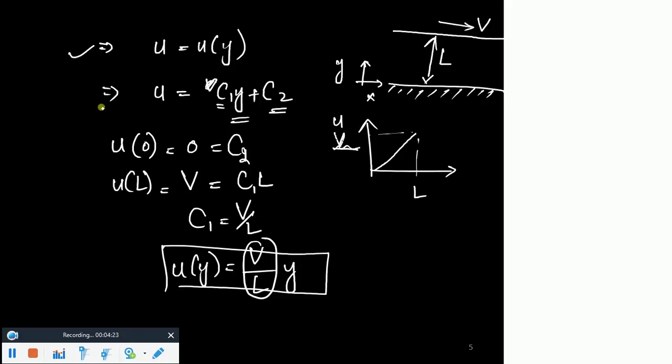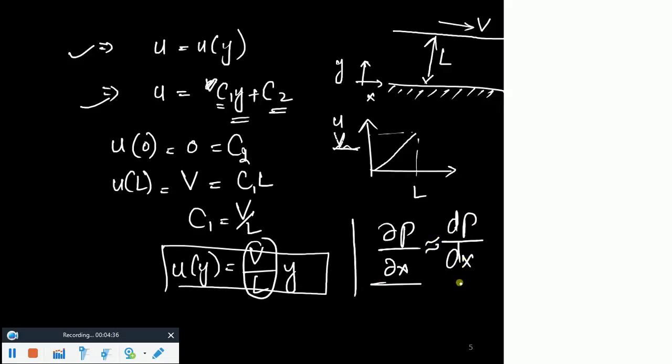So this is about the continuity equation, and those relations are coming from the x part of the momentum equation. The very important thing we talked about in the last class, and how did we say this, was coming from the y part of the Navier-Stokes equation. It means that the pressure gradient is basically only existing along the x direction, not in the y direction, but velocity variations are dominant along the y direction. That's what we talked about.